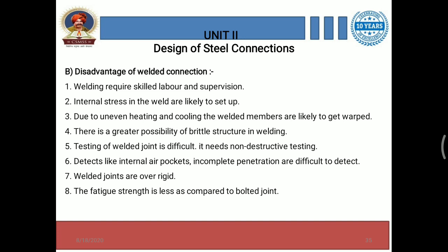Due to uneven heating and cooling, the welded members are likely to get warped. Due to the heating and cooling process they get warped, and they may crack under higher loading. There is a greater possibility of a brittle structure in welding, due to heating and cooling.